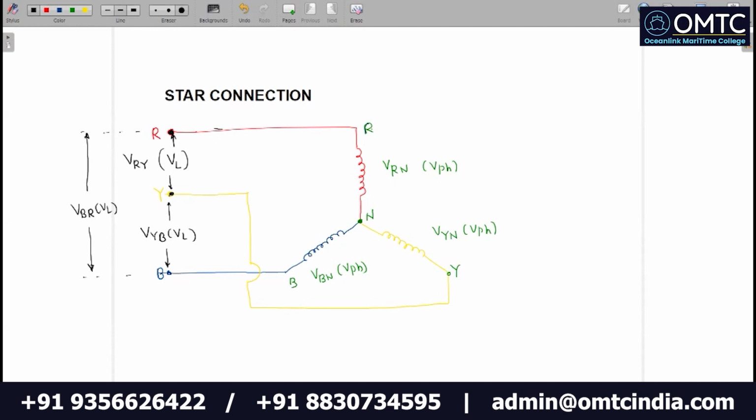And the current flowing here, you can name this as a line current. Here, yellow current, yellow line current. This is a blue line current. Okay, but this current is entering into the winding, it is entering into the load, it becomes phase current here. The current from R to N, we can call it a phase current.